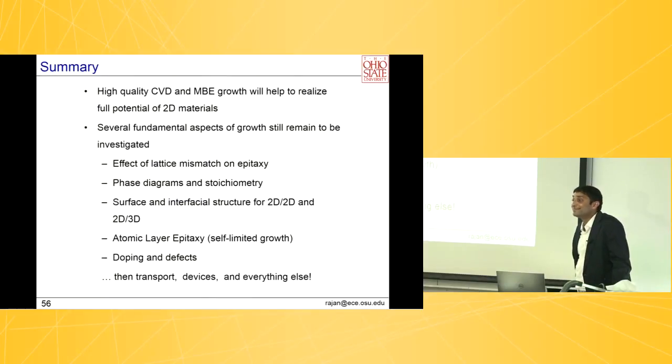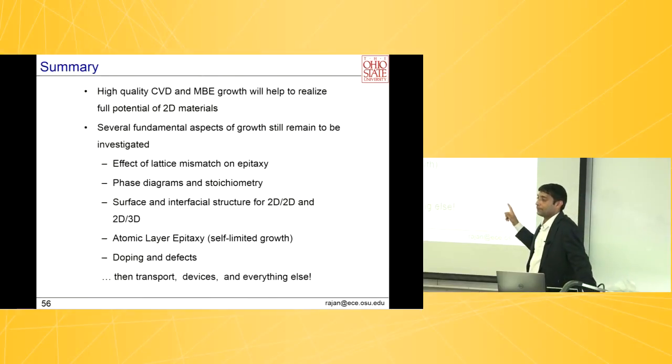I just want to briefly comment on the surface roughness and uniformity of those films. The CVD films, yes. Uniform means they're everywhere. The surface roughness on a 5-micron scale is approximately half a nanometer, 0.5 nanometer, which is similar to a lot of other 3D semiconductors.